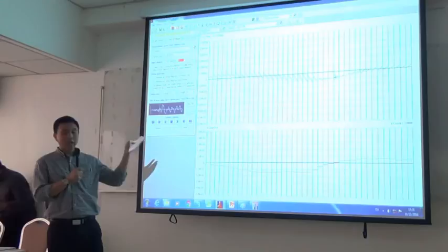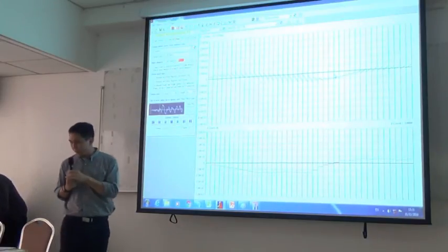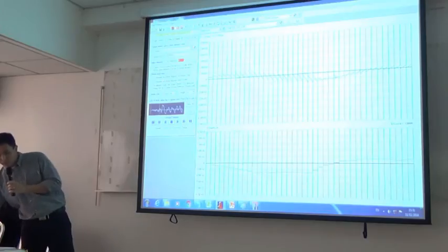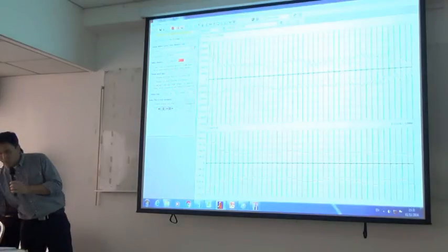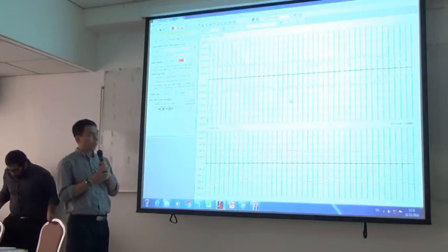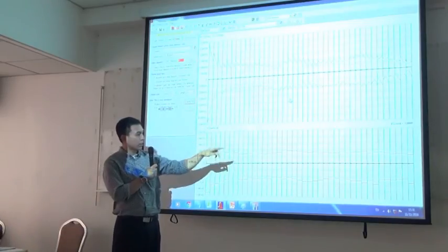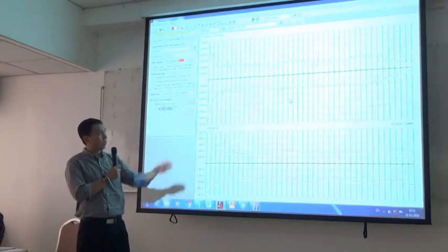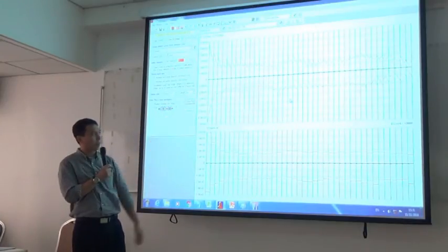check that kind of diagram, step-by-step results, not the envelope. If we check the envelope, for example, we will see like this. This is the envelope. This is the moment diagram M3, and this is the shear diagram. Now we cannot understand what is happening along the height of the building.